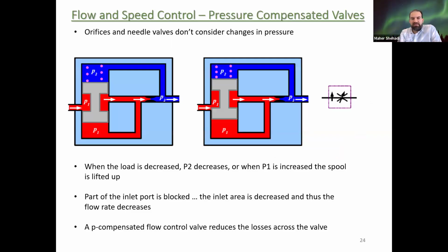Okay, that's exactly what I was talking about. This is the P-compensated valve. Basically, it's a valve that adjusts the flow in order to give you a constant pressure at the output. First, the symbol: it's still variable, but it's automatic control or adjustable. If we look here, what do we have? I have this pivot, it moves up and down. We'll see how it moves.